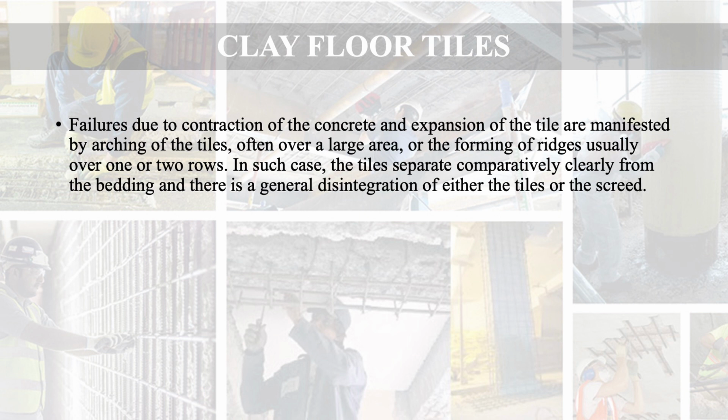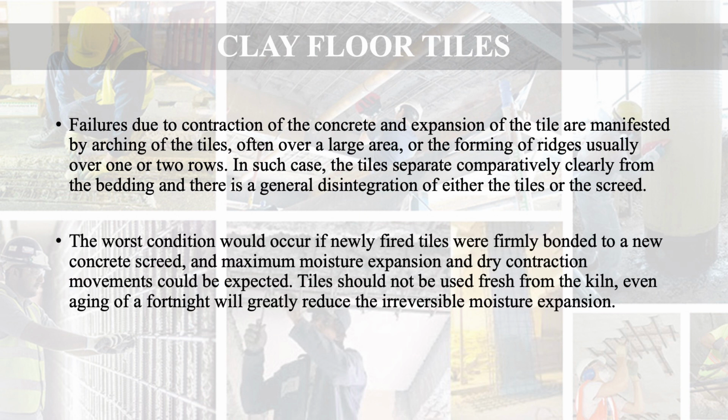In such a case, the tiles separate comparatively cleanly from the bedding, and there is a general disintegration of either the tiles or the screed. The worst condition would occur if newly fired tiles were firmly bonded to a new concrete screed, and maximum moisture expansion and drying contraction movement could be expected.